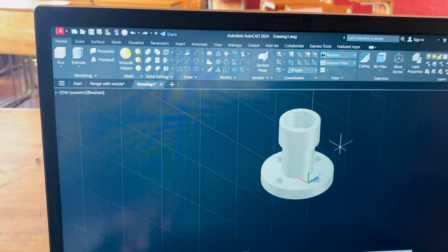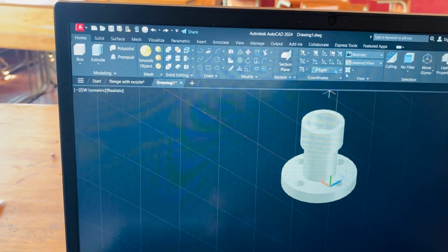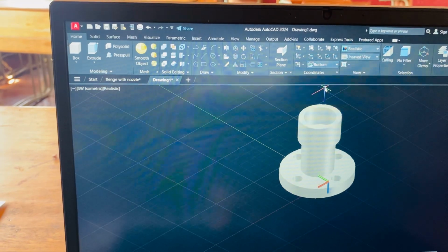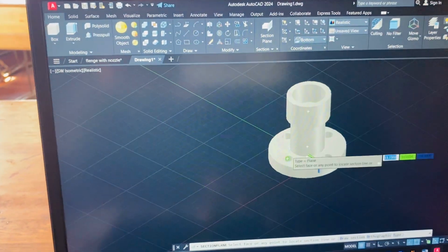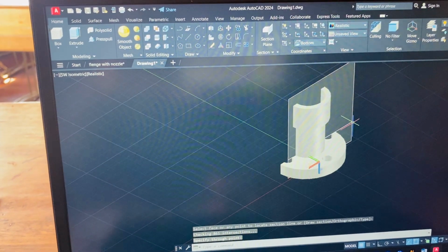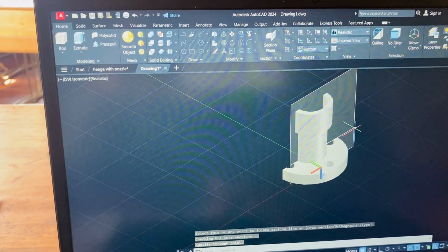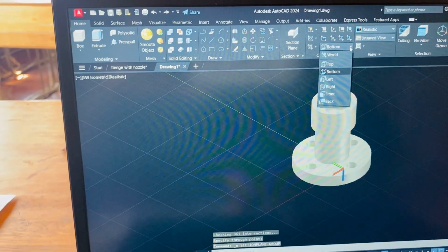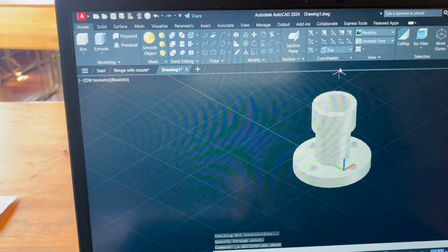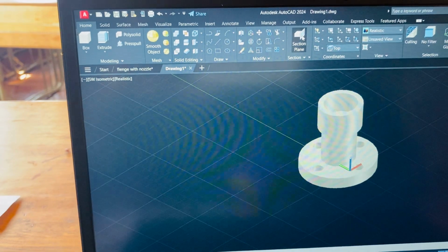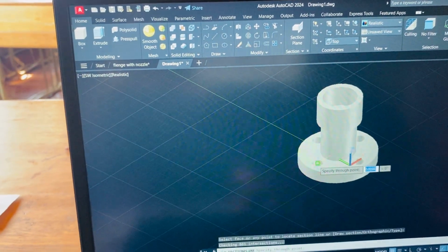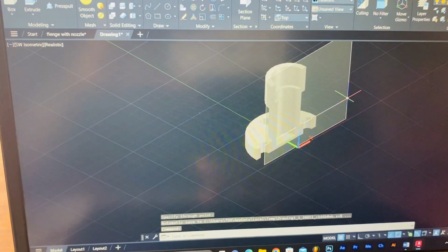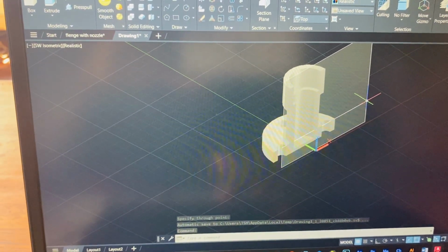Control Z. We change here, we select bottom, and I believe this should do it, but it cuts the other part. So undo, and then we select top, and then this top one I believe is the one that's going to work for us. Yes, you see, this is how you cut it. You put it on the top one and then you cut it.